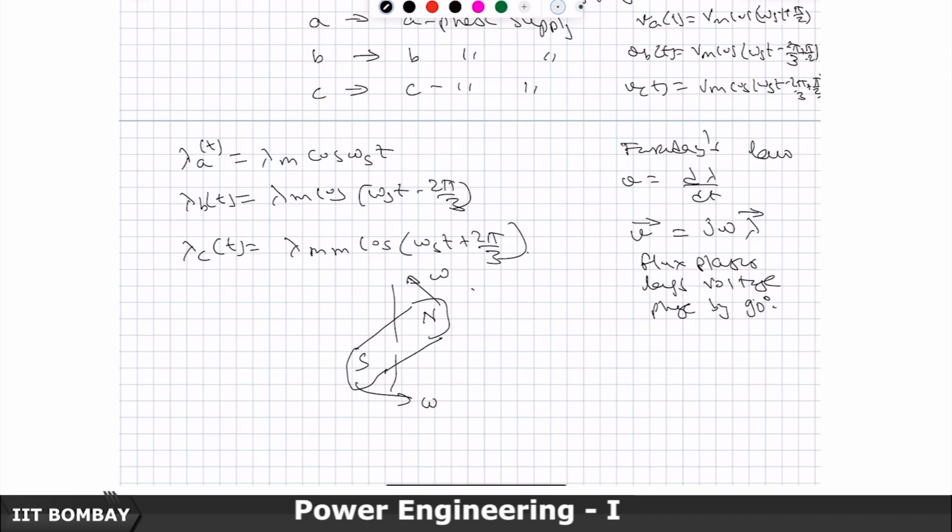Now, this idea that you are able to create a 3-phase rotating magnet without actually having a magnet there, from the stator side, basically means that if on the rotor something similar is done, then it would try to latch on. Suppose the rotor had just a piece of iron, no magnet for the time being. It will feel attracted by this magnet, and so it will try to latch on and try to rotate in this direction.